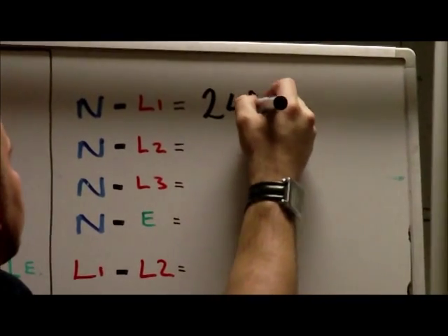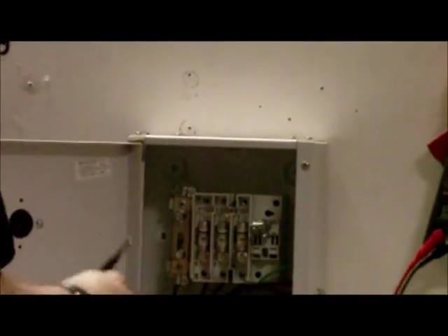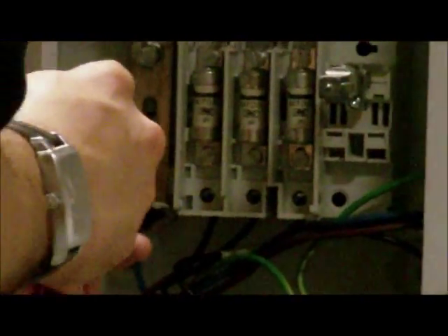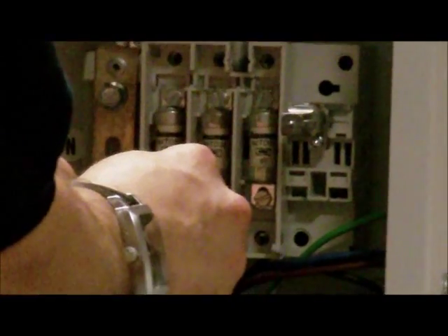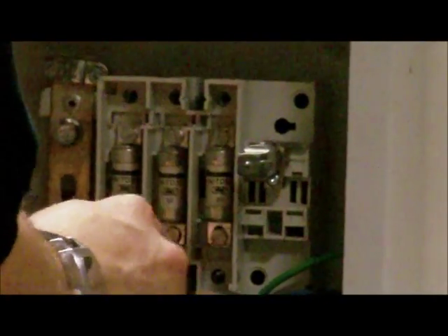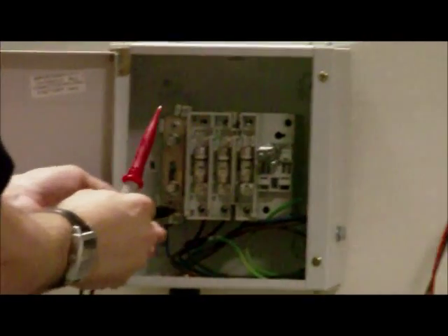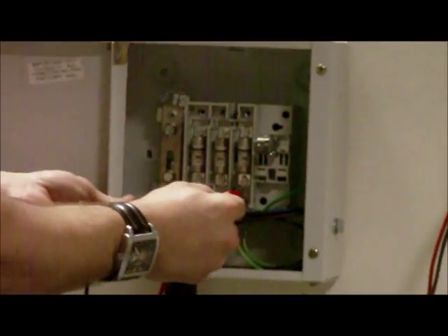So we can go back, let's get the pen, 242 volts. Now it's pretty generic, we're just going to repeat the processes that was previously stated. On neutral again, down to the next line, 245 volts. Now we are expecting, this is a single line supply we're testing because we're going between a neutral conductor and a line conductor.